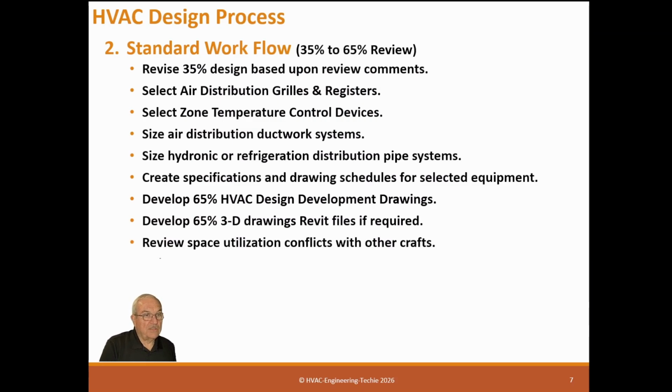Review space utilization conflict with other crafts. And this is, if you have 3D modeling, this gets a little easier because the model will show you crashes where you're conflicting with space allocation. To do that, you have to have everything sized. So all the ductwork has to be sized, and all the pipe has to be sized and laid out, or you can't run a crash program.